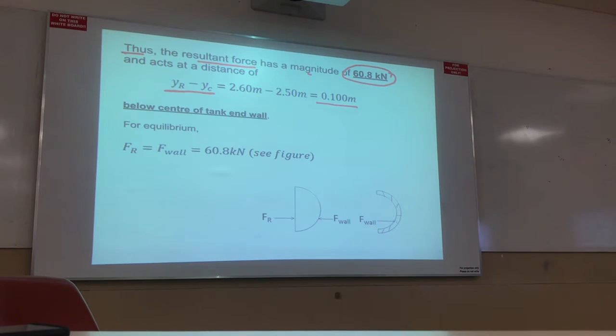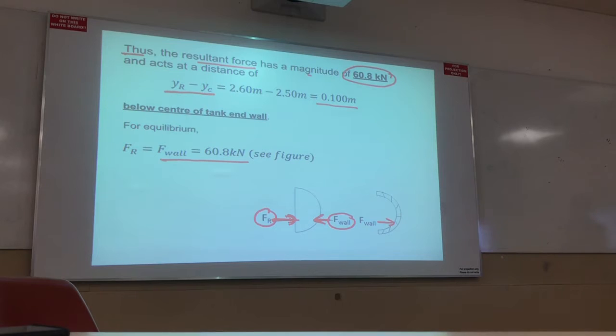Even though there is no water below the center of the tank, they give you the specific gravity of the alcohol, not the density. Because of the force balance, the density times gravity on the wall of the hemisphere is equivalent; the SG and 1000 cancel each other, and F wall becomes 60.8 kilonewton. Simple things. It's not new.